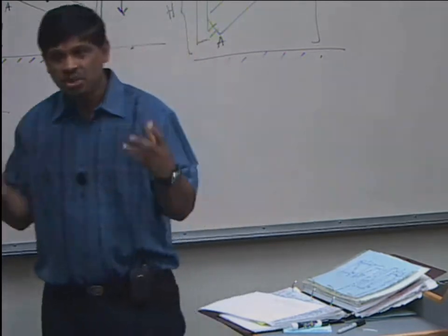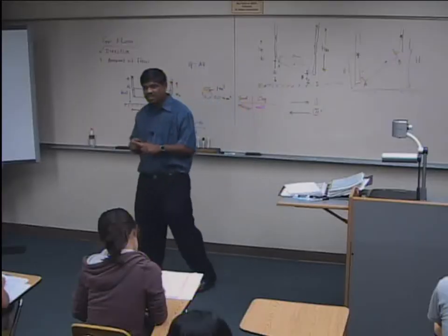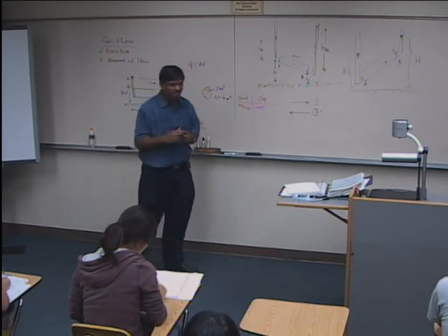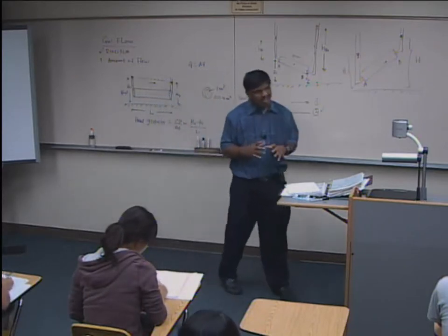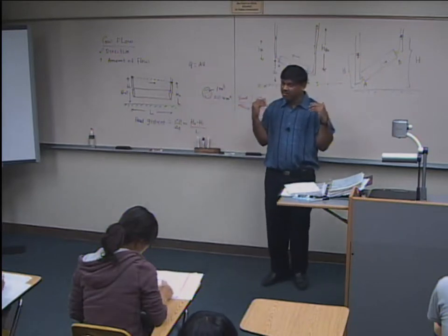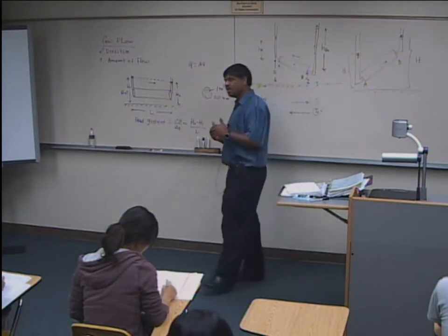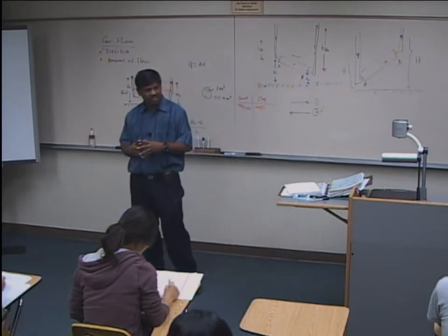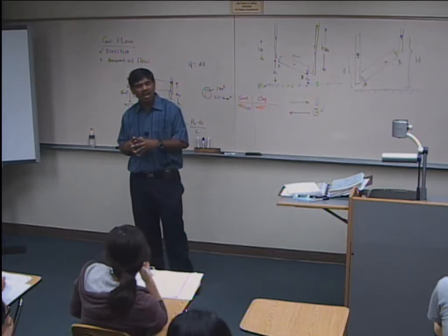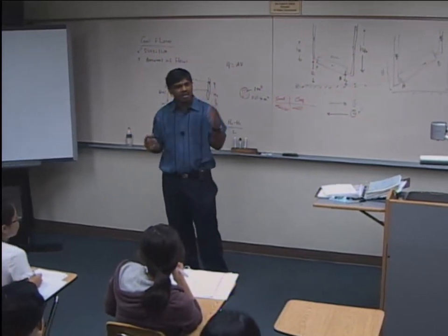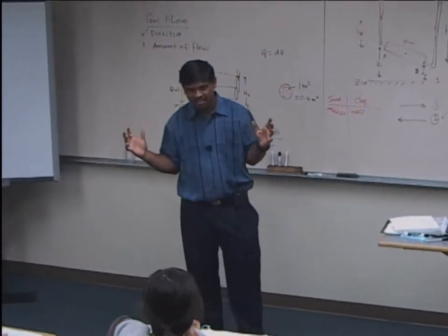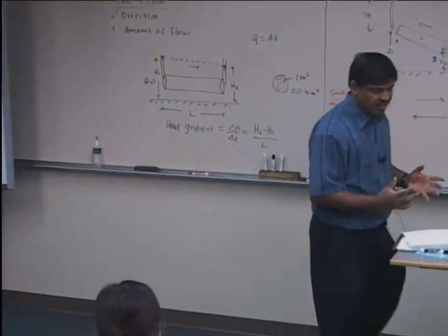It tells how much space is there, but that doesn't mean that is really completely. It's got some minor connection. Later on, we'll talk about it. But in general, they are independent properties. Just like we proved ourselves, porosity is not a function of grain size. Intuitively, we might have thought it's a function of grain size, but it's not actually. Or it's got some mild correlation eventually, but in general, it's not a function of grain size. So it's the same idea here.